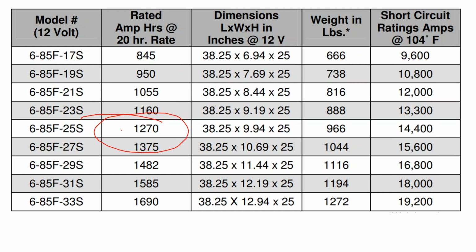As you saw yesterday, the client told us that they did not want to have to rely on a generator in order to live off grid. We're still using the generator to protect and maintain the batteries, but we designed the system so that it would be large enough that if the generator wasn't there, they could still recover during the winter or a particularly wet summer. And so we're looking for a 120 kilowatt-hour battery bank.